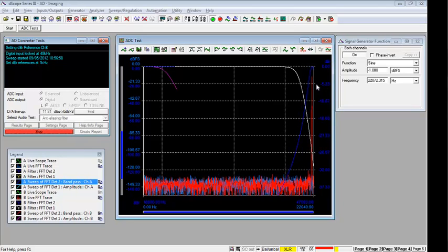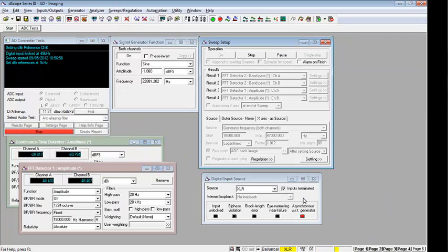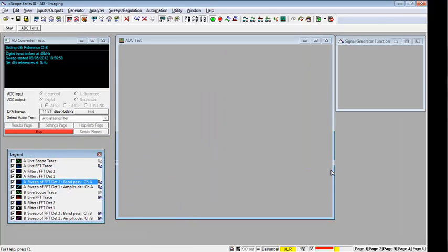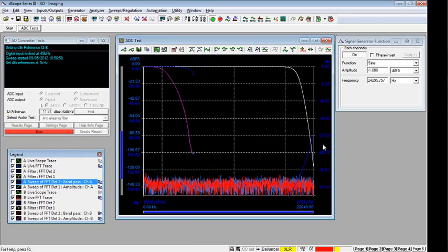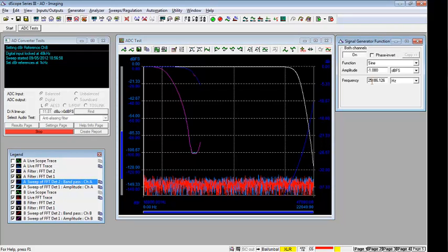Now, this particular sweep has been set up in quite a smart fashion, and there's a script running at each of these sweep steps, and that script is looking at the ADC's digital output frame rate, looking at the signal generator frequency and saying, well, hang on, we've now gone above the Nyquist limit, we're at 26 kHz now, so this filter starts to track back downwards towards the upper limit of 20 kHz that we normally consider to be the limit of human hearing.